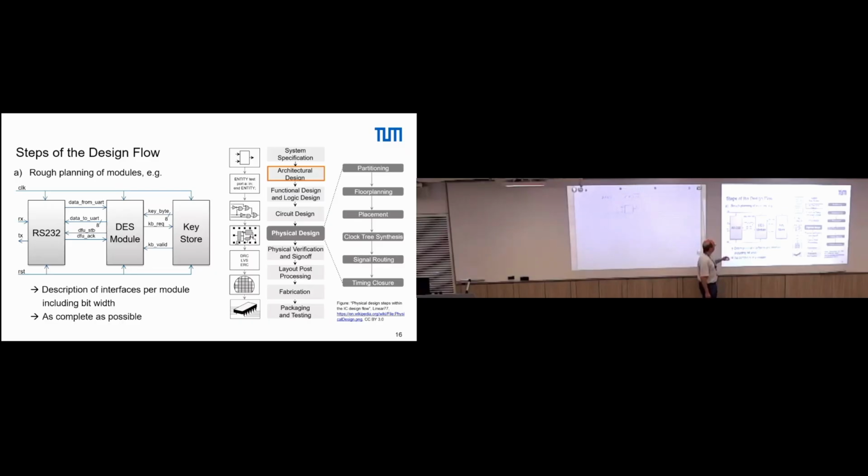What you can do is, if you have sufficiently small building blocks, you can test and verify each individual building block, and then build them together. On a higher level, at some point, you only do something like random testing, so you only apply random patterns and try to find the corner cases, to get some confidence that everything works, but you do not do exhaustive testing anymore. Good.